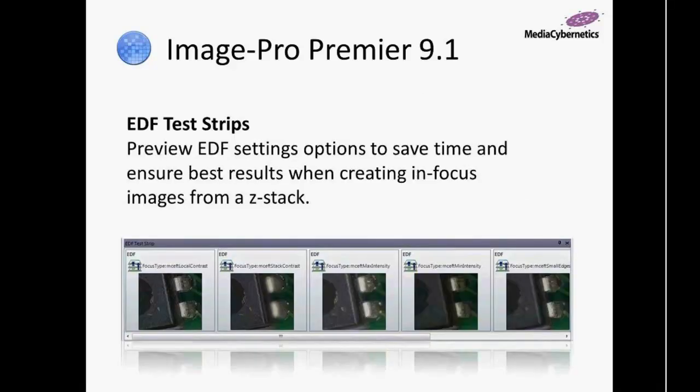In addition to this new feature, we're bringing back an old one actually, our EDF test strips, and this is for extended depth of field processing. If you have a Z-stack that walks through a different focus plane in each one of the planes, let's say in this example, a circuit where you're looking at different focal planes, and in order to get them all in focus at one time, you want to capture different planes and then combine all those into one in-focus two-dimensional image. Using the EDF test strips makes it really easy to find the best settings to